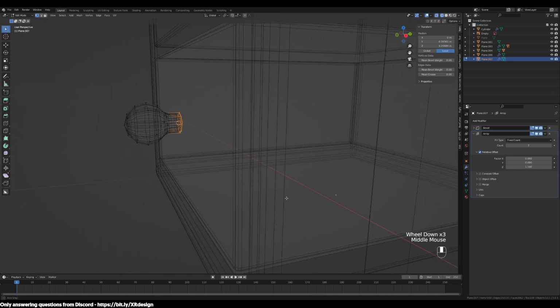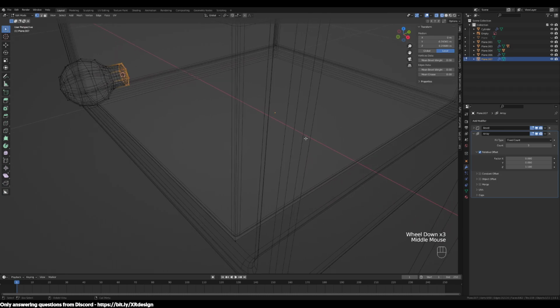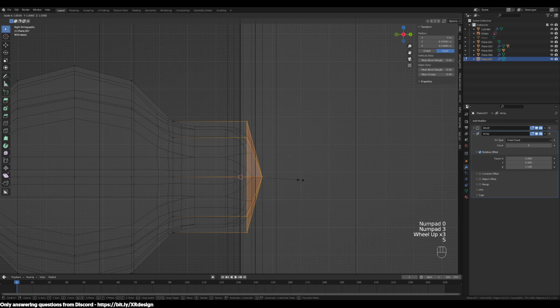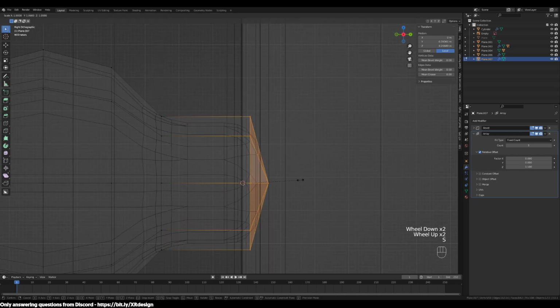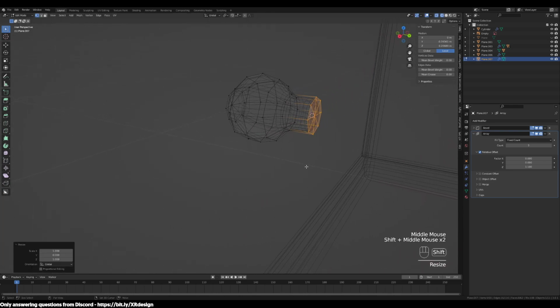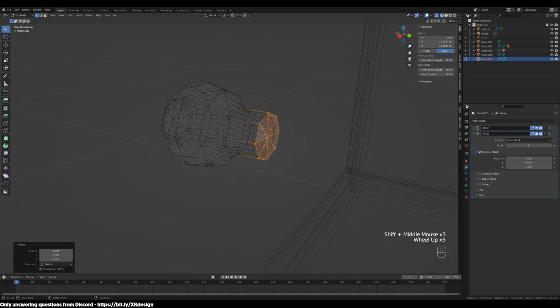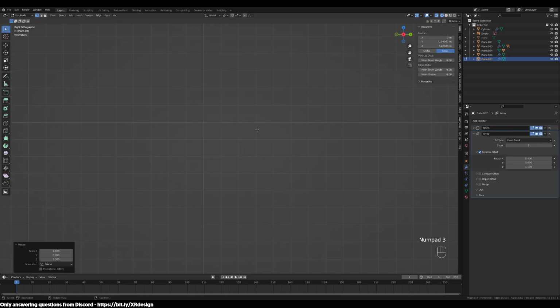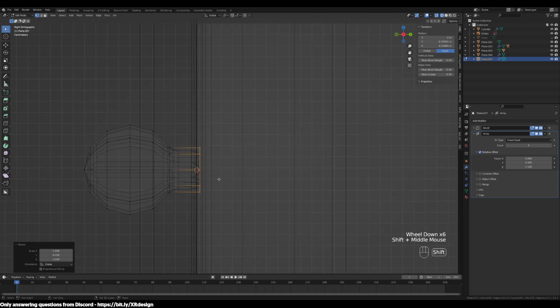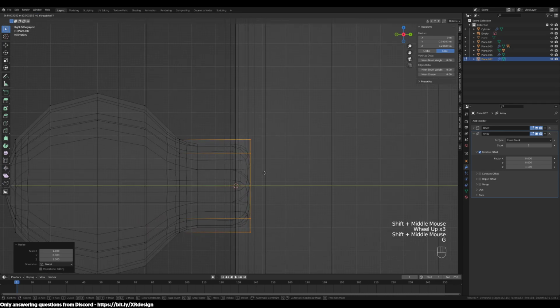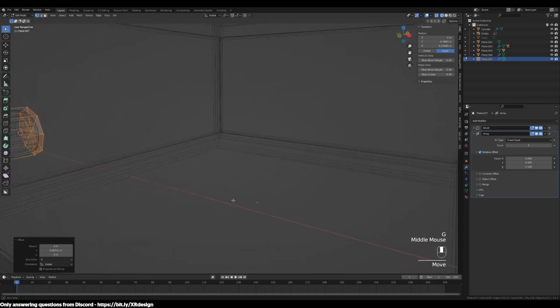And in this case, we want to do that against the axis. So again, go to side view, S, X. And if you hit 0, that's X. Oh, sorry, we're going to do it against the Y. S, Y, 0. That's just going to completely flatten that surface. So you get a flat surface there. And I'm just going to make sure it's going into the drawer, like so.